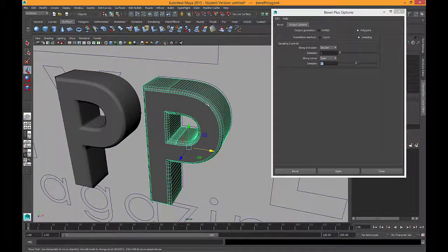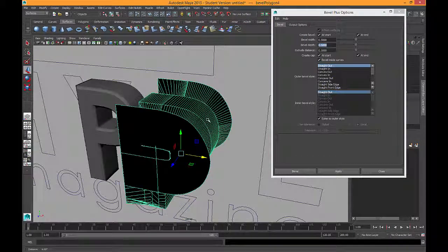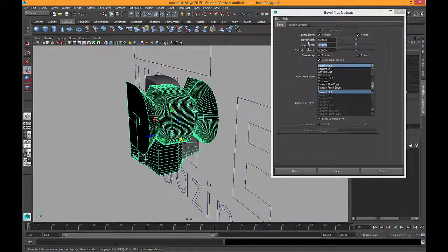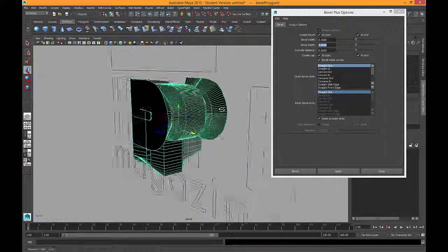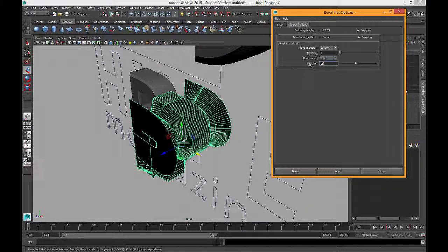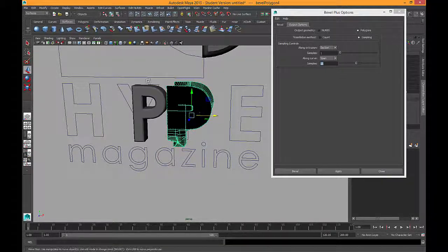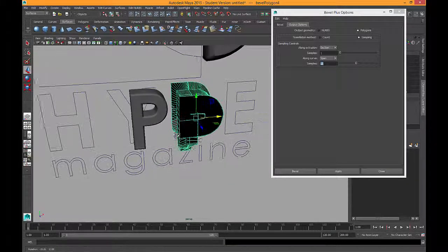What we can actually do, there's one way I can force it. Let's change that to a value of maybe 0.5. I'll reset this back to 0.5, see if this will do it. There we go. So if your extrusion, your bevel and width value here is too big, it'll do that. You'll get this big scrambled up mess. The same thing can happen if this span samples number is too high. So you have to adjust back and forth until you're happy. And just do it with one letter, okay? And the letter should be curved when you're testing it, okay?